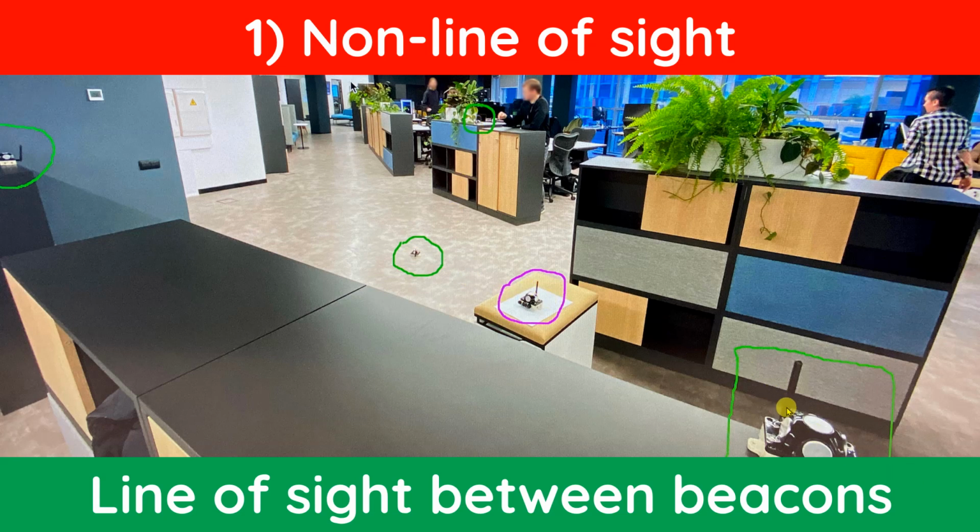So it means that when the table of distances is being built, the system is trying to measure the distance from this point to this point and from this point to this point. When this beacon is transmitting ultrasound, this beacon can hear. But when this beacon is transmitting, this beacon cannot hear, because the microphone simply cannot look below the horizon. And the horizon for this beacon is this. So this is below the horizon. Okay, this one is already enough for the system not functioning at all.